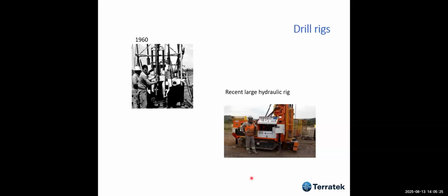For hard soils, we use the Denison sampler, which we're going to address. And if we have silty sand, etc., a split barrel sampler could be used. And once we get into very hard soils, we have to use rotary drilling with special samplers for rock sampling.